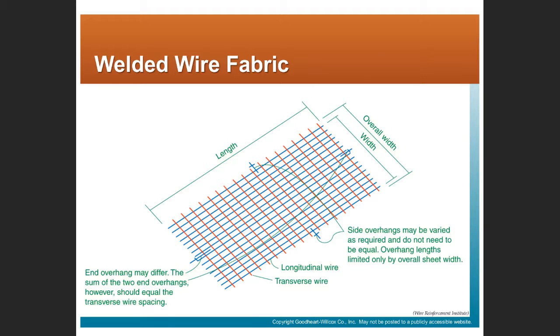If you're pouring a basement floor slab, or a slab on grade in residential construction, I would easily expect you to see something like this. And that welded wire fabric will be laid on something to make sure it's positioned correctly in the concrete, right? So it's not at the bottom. You'll see that there are some other pieces of metal that help position this correctly.